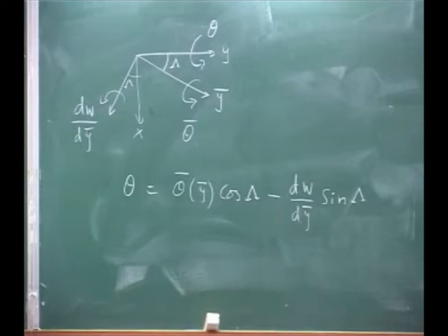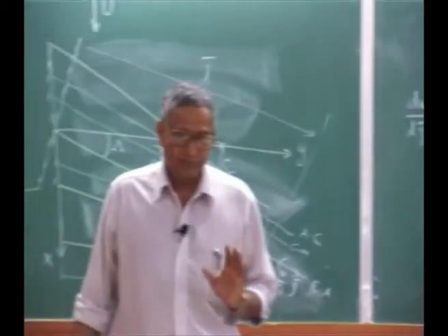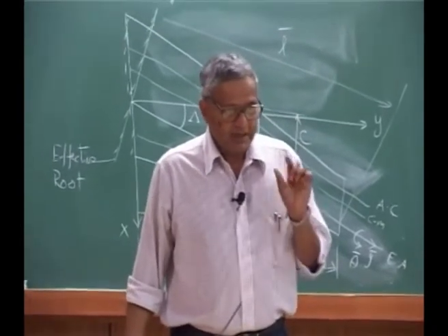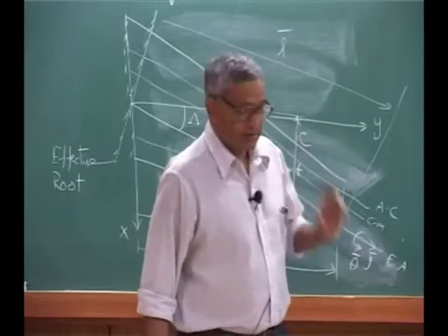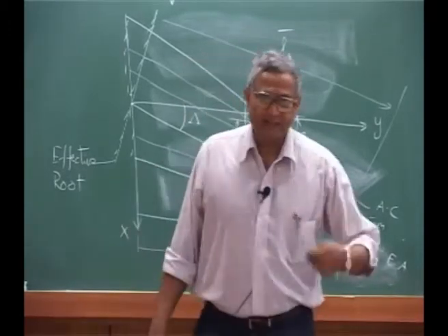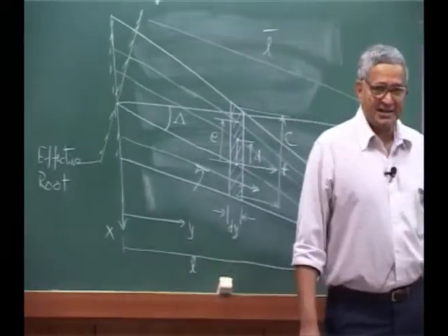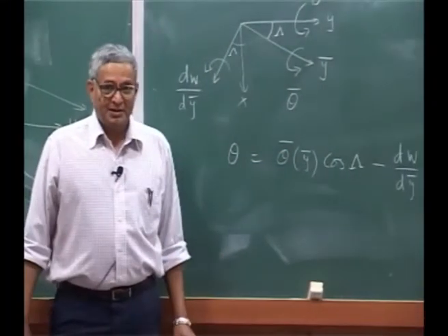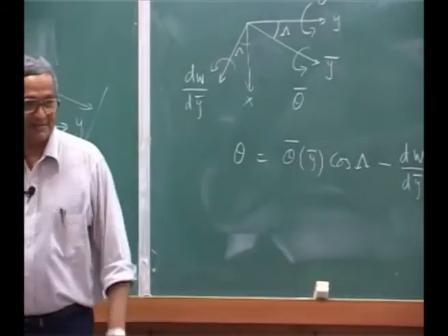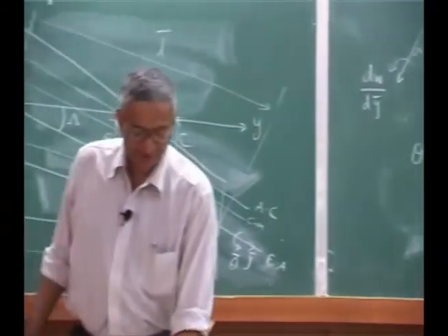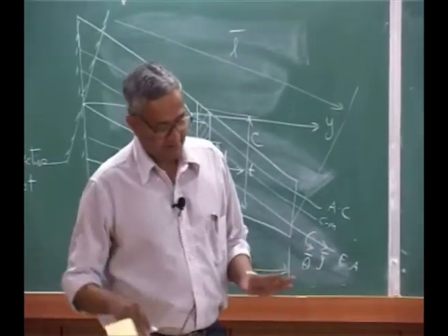But how do I get the lift? Okay. Now this is where I will do a little bit of some kind of equivalent lift formulation. Okay. I am using equivalent lift formulation, and that is what will be used, because you need to know what is my CL alpha. Is it like I will just directly multiply CL alpha here, or the CL alpha is different because of the speed. Okay, this is done for an infinite wing formulation.